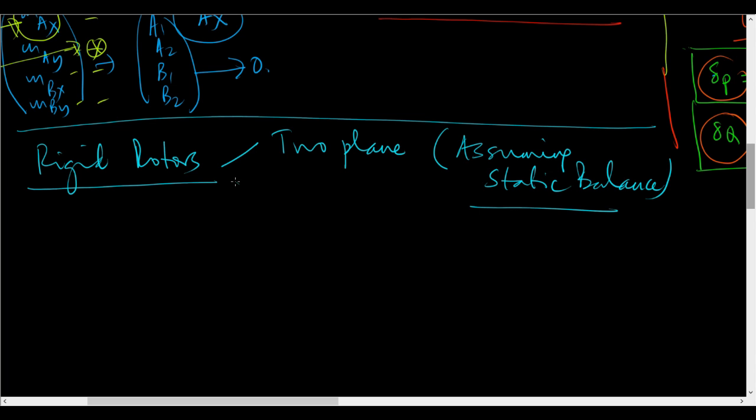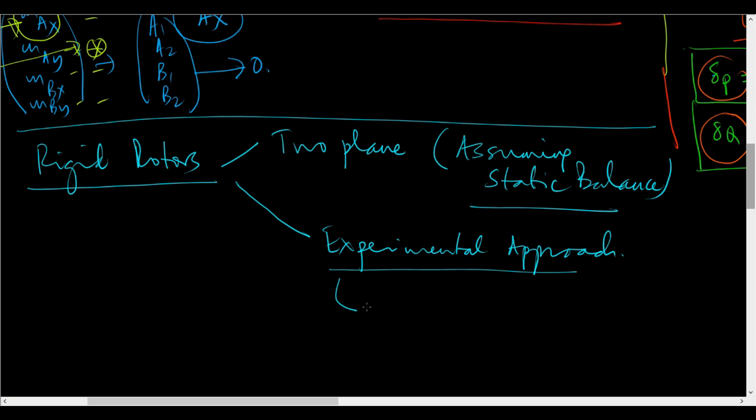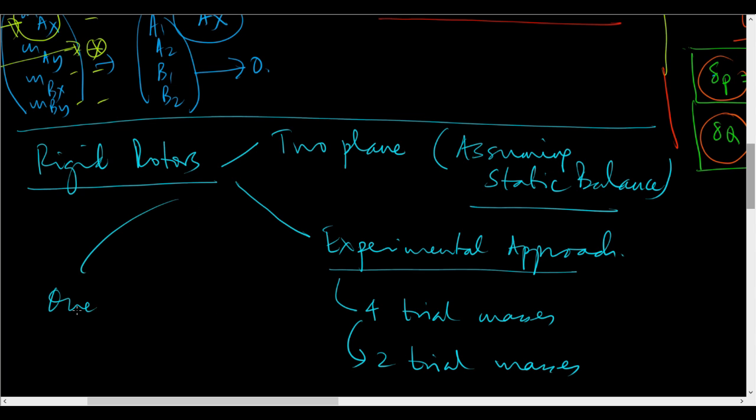And then experimental approach. We have not actually done it in a laboratory, but that's what we have done here, experimental approach. And then with 4 trial masses and then with 2 trial masses. And then we have done one plane or single plane, and we have used single trial mass.